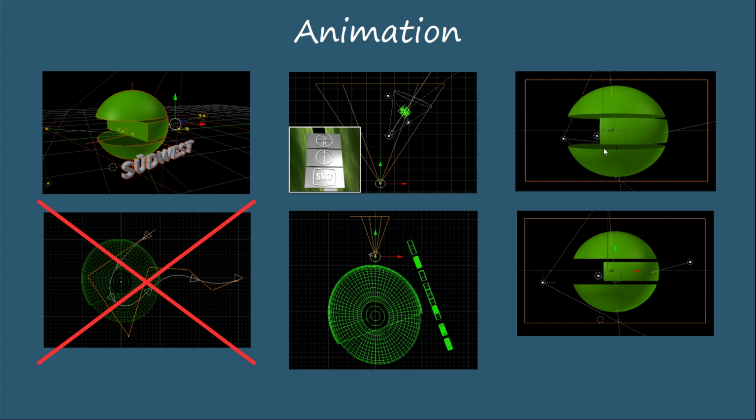I animated the focal length from 35 millimeters and changed it to 100 millimeters for the final shot here. And at the same time, I moved and animated the camera and moved it away from this 3D logo. So 2 different effects, changing the focal length and also changing the location of the 3D camera.